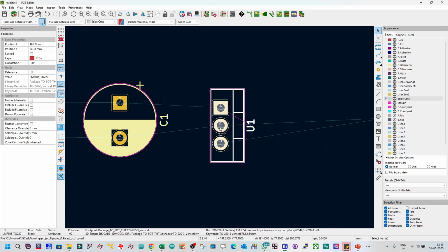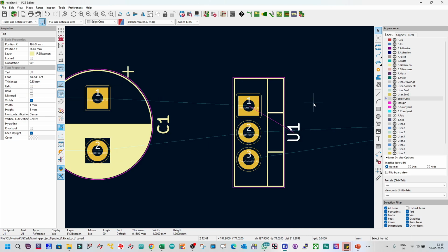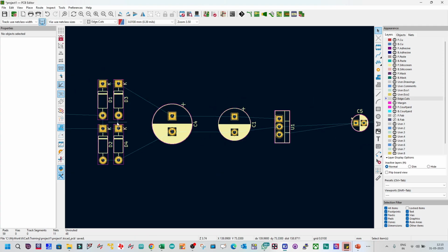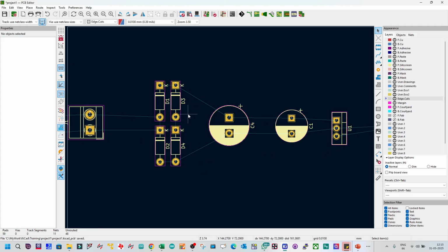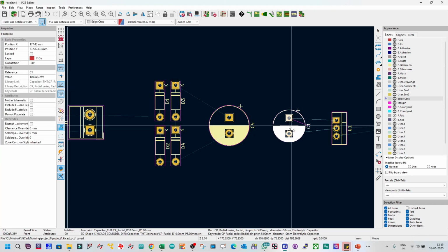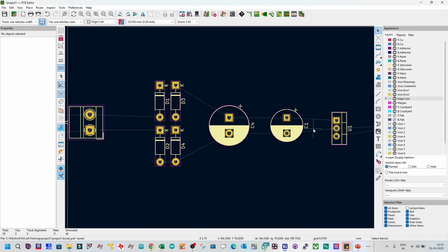See, guys, I'm just making it like 1:1. Are you able to see this? Yes. Routing: it comes here, it goes to here. This guy comes here, it goes to this guy. This will all be covered in a single layer. There is no cross routing happening. You have to be very careful if there is cross routing. You should do a placement so that there is zero cross routing. The target should be to achieve zero cross routing.